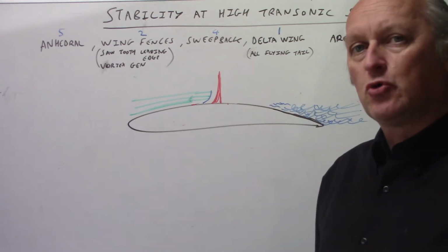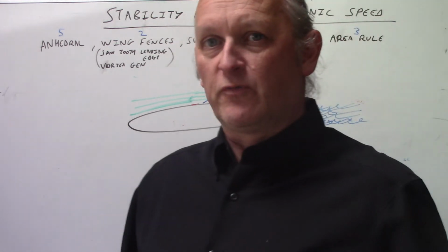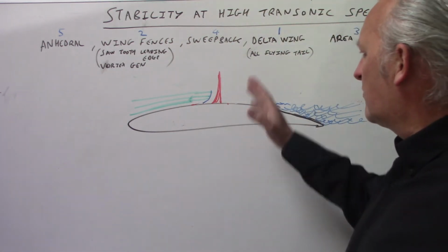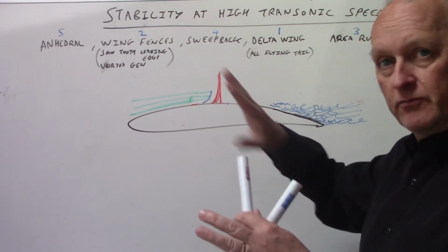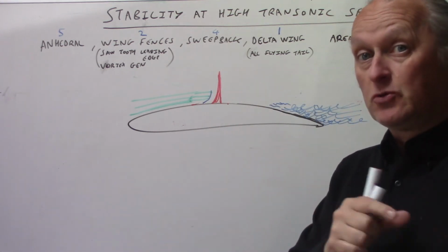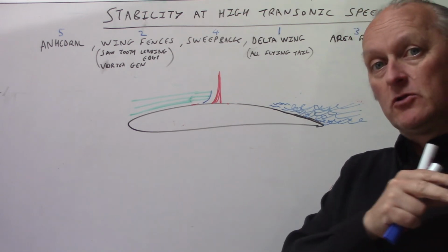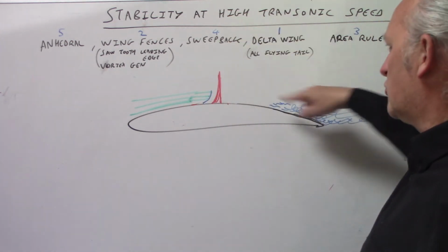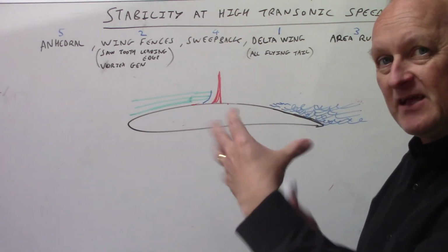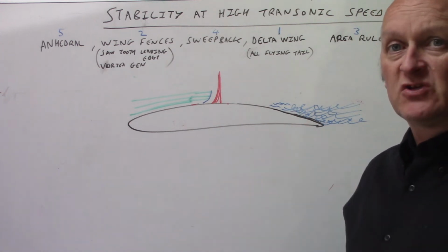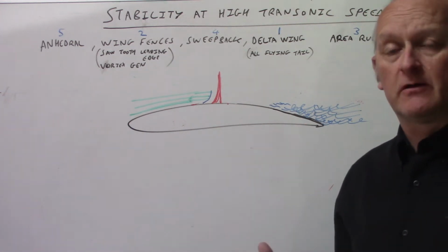Okay, so the shockwave forms at that maximum curve point and kind of hangs around there, right? What you've essentially created is a little cone, or a point of compressed air, that is now attached to the wing. It's stuck to the wing and it is moving along with the wing. Now people think that the air has to flow above the shockwave and all that. Air can flow in and out of a shockwave, but the shockwave will slow it down while it's compressing it. So it acts basically like an air brake. Okay.